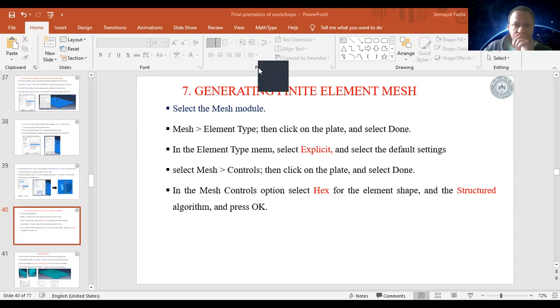And now here we have other duties than meshing only. We have to select whether the analysis is standard or explicit. The identification will be here. So our analysis is considered as explicit analysis. By default, our case will remain a standard analysis, so we have to change that. In addition, the material type will be assigned here.